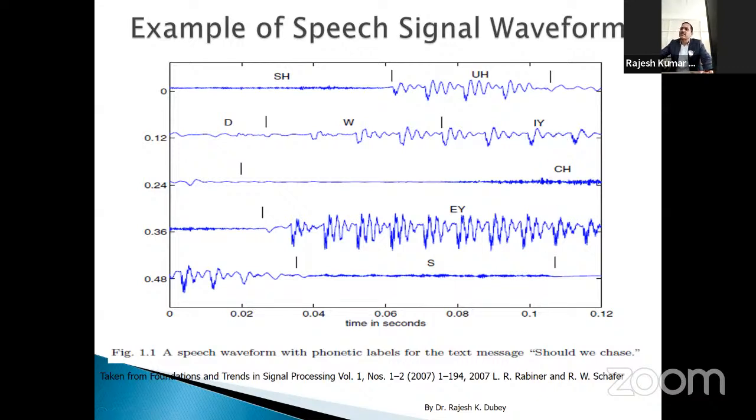So I hope you can understand what speech is, what a phoneme is, how it is broken into phoneme level, and which phonemes sound voiced and which sound unvoiced. The unvoiced part is noisy. The voiced part is quasi-periodic with high magnitude. High magnitude means a high energy area. Some periodicity is there, and energy is more. So this is the first observation on analysis of speech signal at the phoneme-based level. I think you must understand this idea.